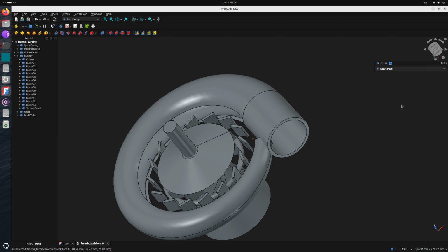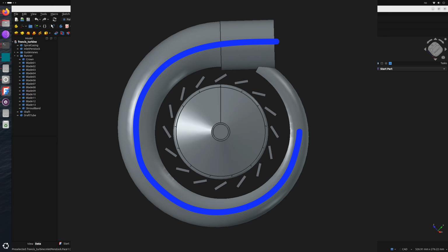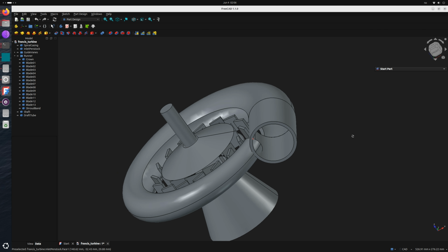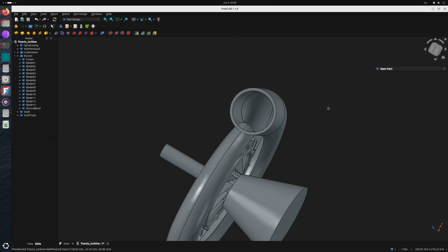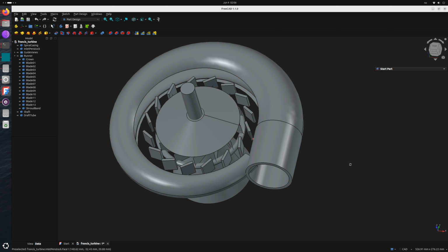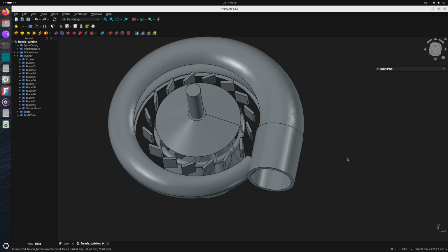Instead of a jet, water spills inwards through a scroll case and guide vanes onto a runner shaped like a curved seashell, running on pressure and flow at once. That is why it's so flexible. A few dozen meters of head up to several hundred. Which is why Norway's biggest, highest output stations are all Francis.